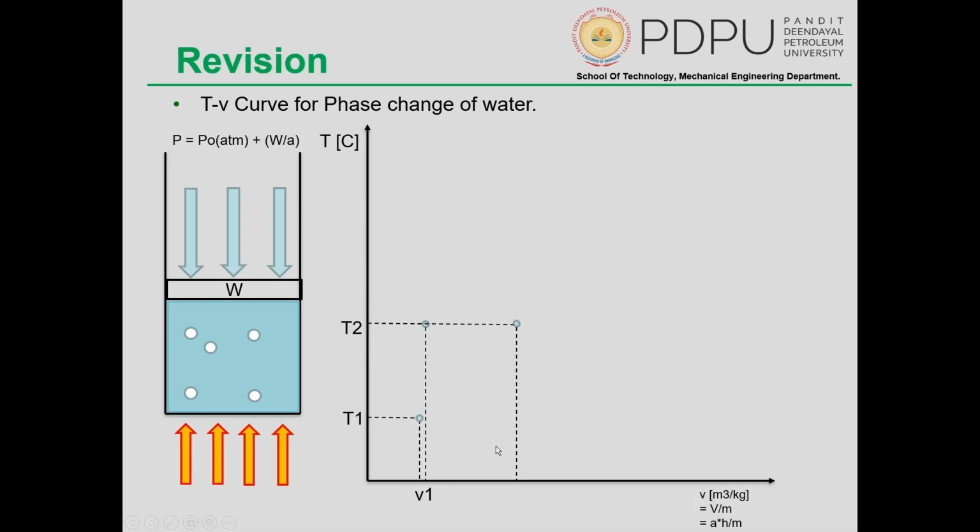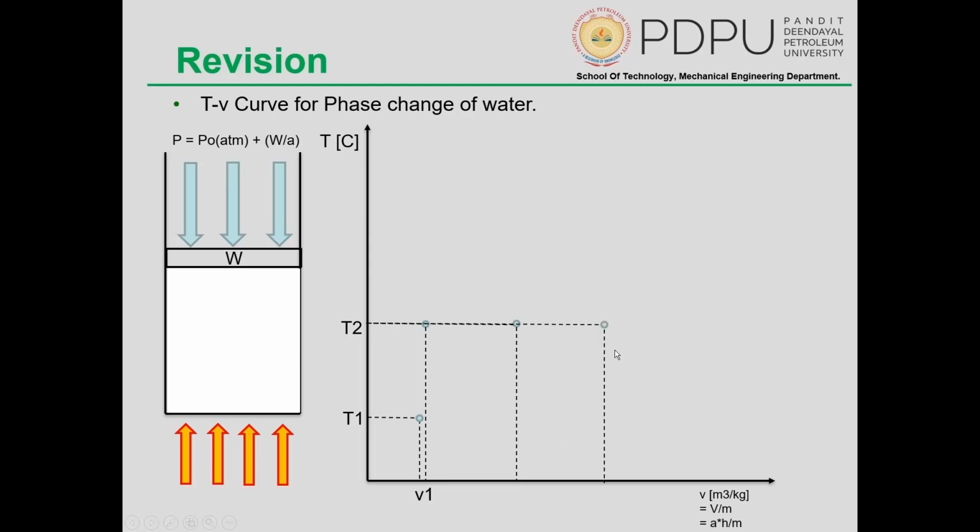So as we move ahead, we reach a certain point where bubble formation, or basically the steam formation out of the water, is happening, and we will see a mixture of steam and water. If we continue to do it, the entirety of the water will be evaporated and only steam will appear. That can be denoted by a certain point here. A point where the complete liquid section is converted into steam is called saturated vapor.